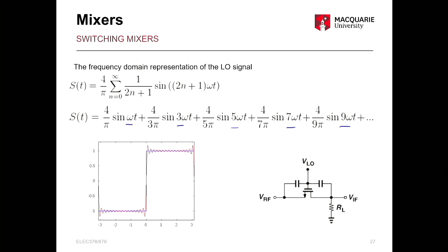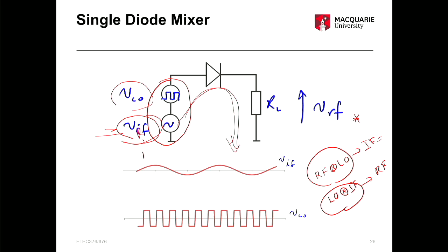So this is a way to implement that using a diode. This is the simplest way. This is not a very robust way to implement a mixer, because now you have a big isolation problem between output and input. Your output gets fed back to the input, and also input comes to the output. So there will be interference from the input, and also your antenna's sensitive electronics can get damaged by the interference from the output. So conceptually it will work, but this is not a very practical circuit.